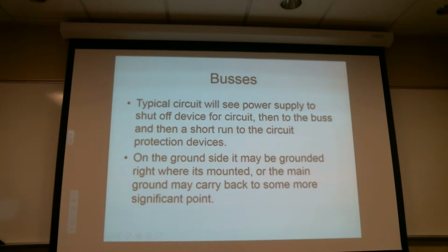That way, that big positive lead is as short as possible. If it shorts between the battery output and the master switch, you can't shut it off. So if you keep that very, very short, the potential for it to get shorted is very little.